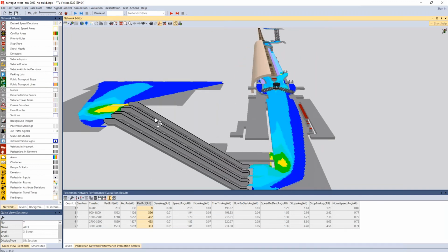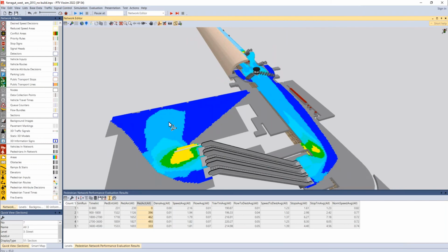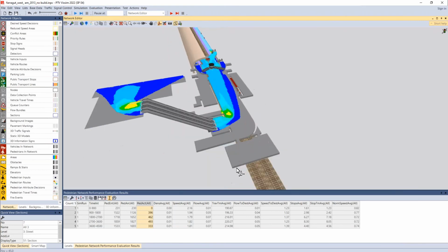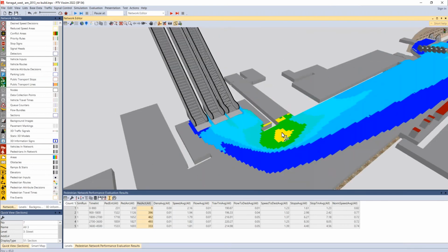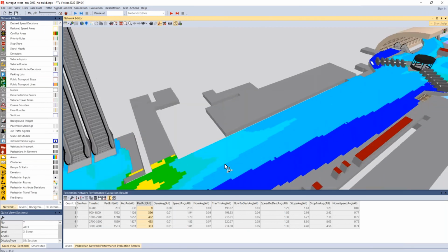And you can see where the hotspots are, right? Now, in my experience, hotspots typically will show up in 2 key places. One is at obvious bottlenecks like the top of stairs or security terminals. But one that's not so obvious that people need to consider is right angles. Right angles with pedestrian flows typically will create a lot of congestion, because everybody wants to cut that corner. And so the people on the inside typically get boxed out or get stuck and have to slow down.